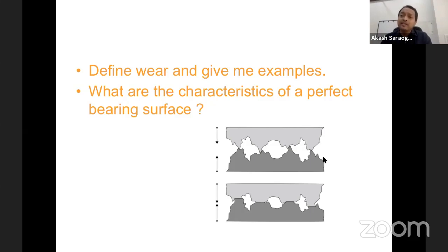Now, types of wear and modes of wear are two different things, and this will be particularly asked in your exam with regards to hip replacement. What are the types of wear, what are the modes of wear? It is very, very common to interchange these two things in the exam. What are the types of wear that we talked about? Adhesive wear, abrasive wear, and fatigue wear. But what are the modes of wear? Modes of wear are four types: an articulating surface with another articulating surface, which means the head of the femur along with the acetabular cup. That is mode one wear.